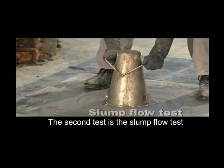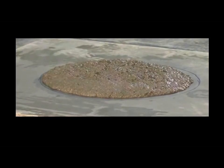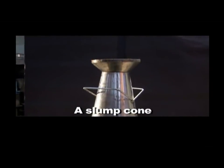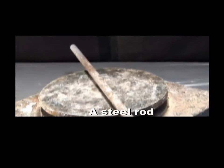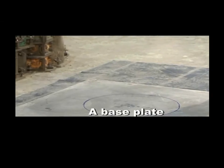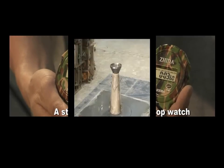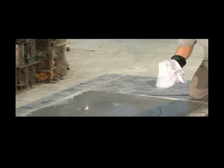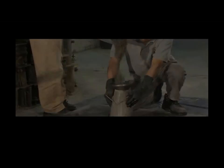The second test is the slump flow test, which measures the ability of SCC to flow. For conducting this test, you will need a slump cone, a leveler, a steel rod, a measuring tape, a base plate, and a stopwatch. Again, we follow the 3-step procedures: preparation, molding, and measurement.